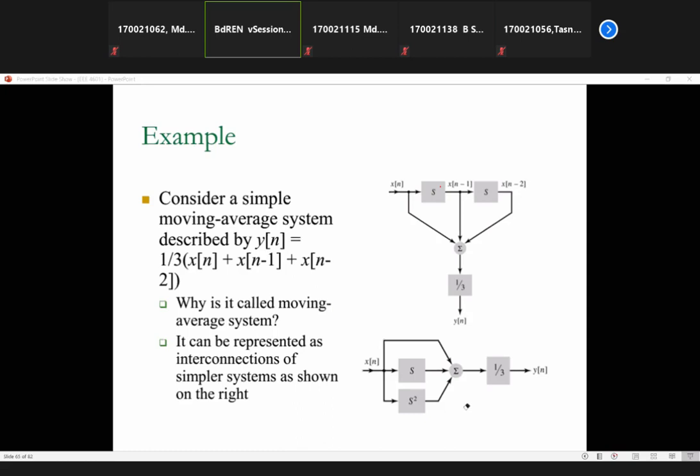As you are adding your solution in every time step, if your algorithm is poor in performance, then what will happen? At every step, it will be giving you an error, and that error you are adding at every step, and eventually you are amplifying the error as it progresses in time in computation. And eventually what will happen? Your total solution will be getting unstable and useless. Although the algorithm is very simple.